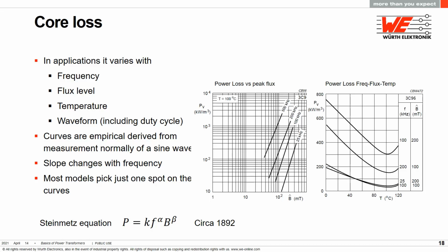There have been a lot of modifications to the original Steinmetz equation in the hopes of using sine wave parameters to estimate rectangular wave results. These have met with varying levels of success and adaptation.